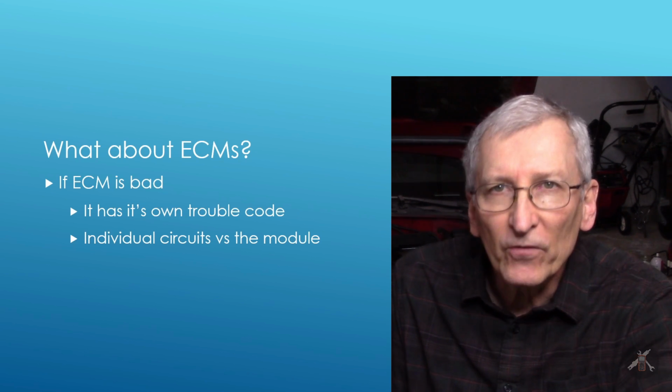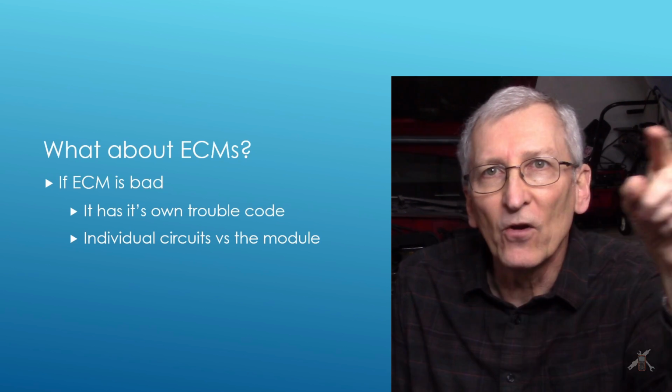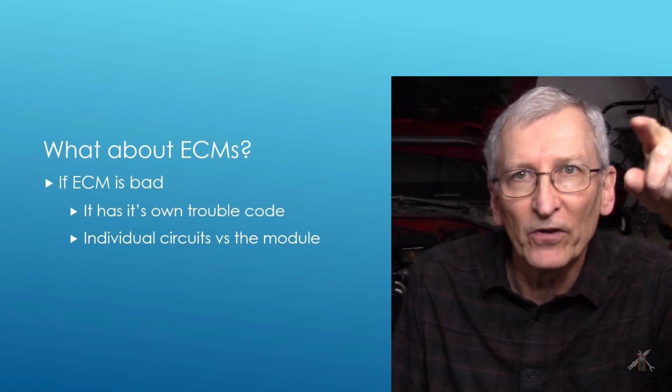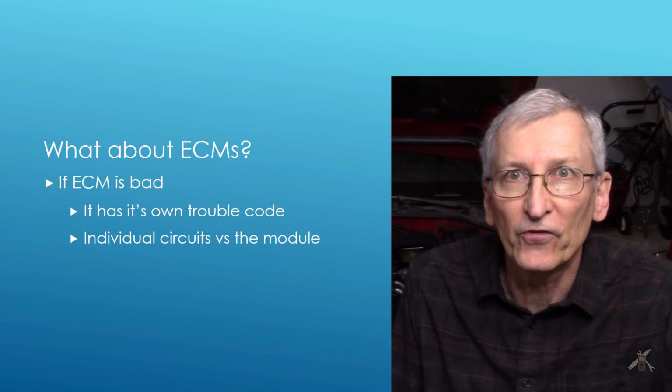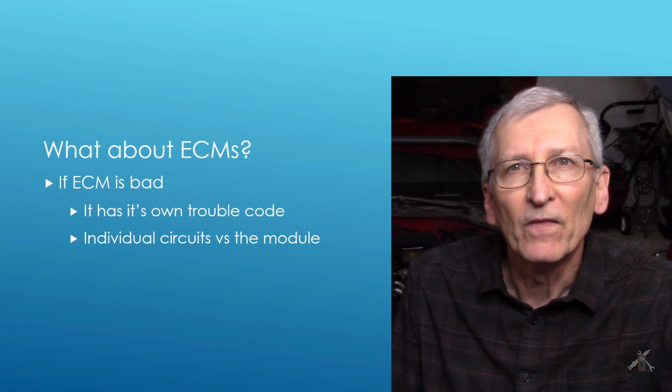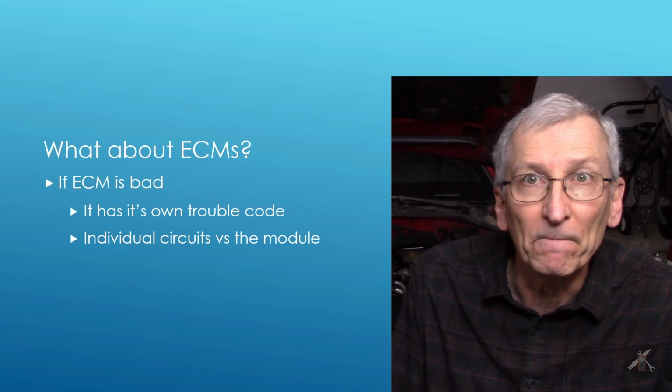If you go through the service manuals, you'll find that if you go through the trouble tree and say, okay, I'm going down the EGR driver and the EGR driver's not doing this when it's supposed to, that indicates that circuit is bad in the ECM.